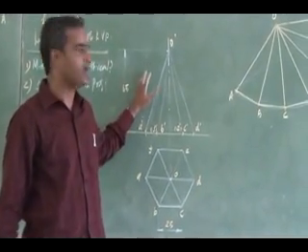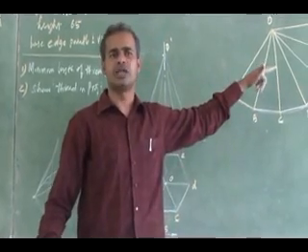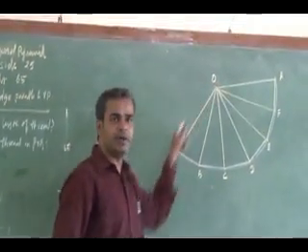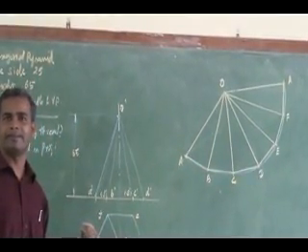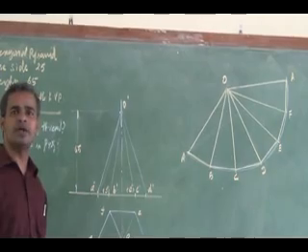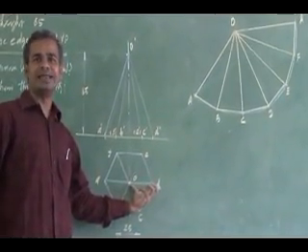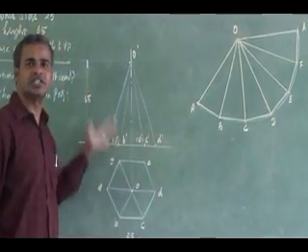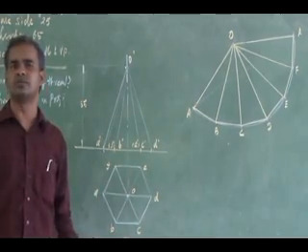For this pyramid, I have drawn the development. For the development of a pyramid, I need a true slant length. OA is nothing but my true slant length. Do I have a true slant length here? Directly, I have a true slant length in this problem. You can see the OA and OD slant edges. In this orientation itself, it is parallel. I need not rotate, similar to the previous two problems, right?